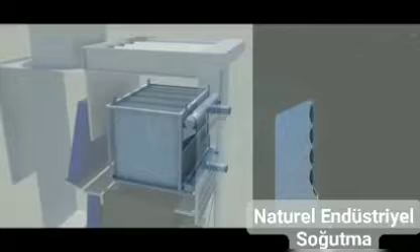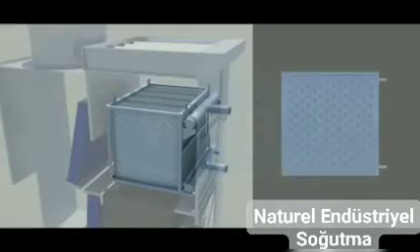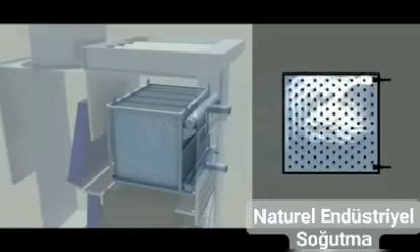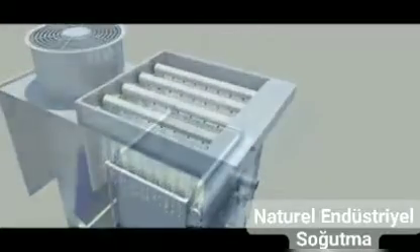During operation, the high-temperature gas enters the channels between the two spot-welded plates, forming a single cassette via the top header. The weld spots interrupt the gas flow intermittently, thus creating a turbulent flow pattern within the channels. This flow pattern does not exist in the conventional coil-type condenser.